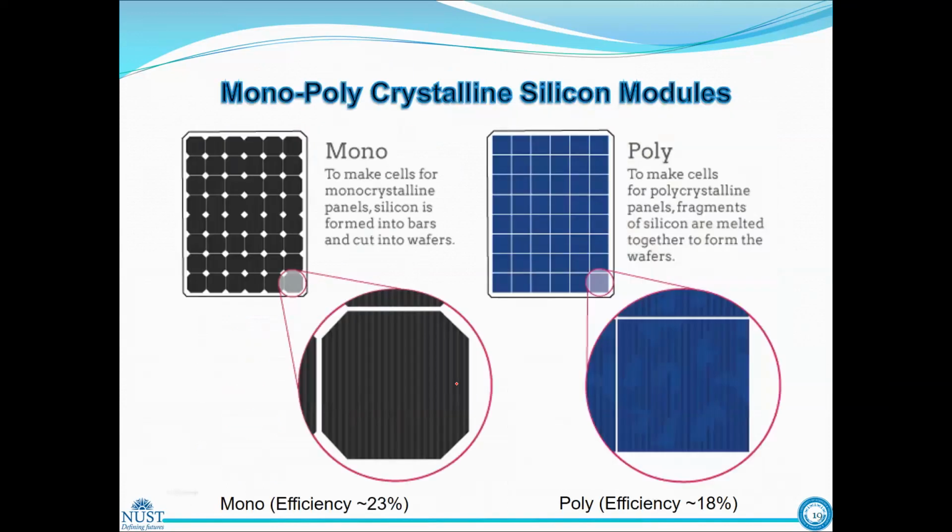Okay, efficiencies of different types of photovoltaic modules. There are monocrystalline and polycrystalline photovoltaic modules, which are very common in the commercial market of this field. You can see that mono appears black, a very homogeneous color, and they can have cut corners, not much, but they usually have cut corners. They have record-breaking efficiencies of up to 23% at module level.